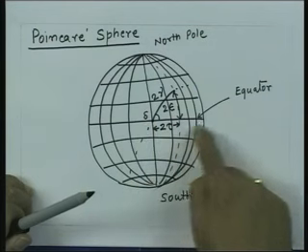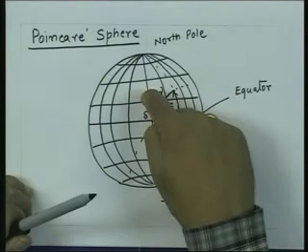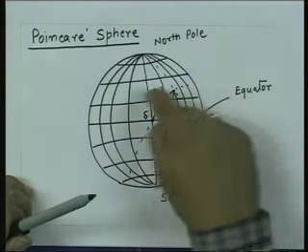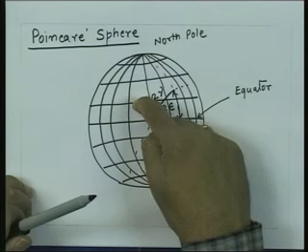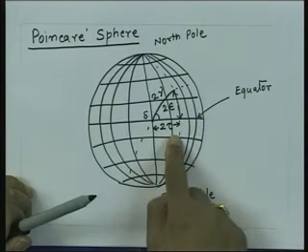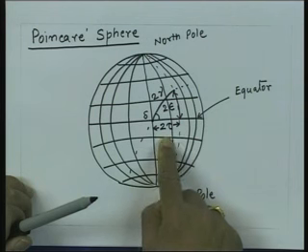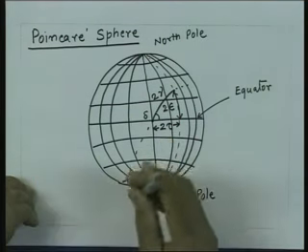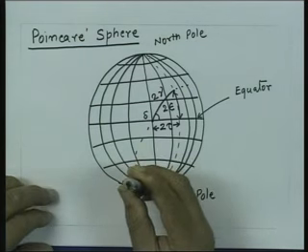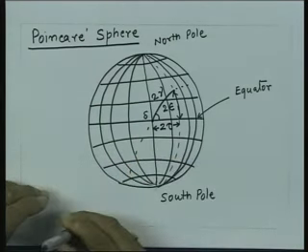When I go all the way around to the back side of this, this will become 180 degrees. So, you will get 2 tau equal to 180 degrees. So, tau will be equal to 90 degrees. That is, the tilt angle will become 90 degrees, or the line will become vertical.